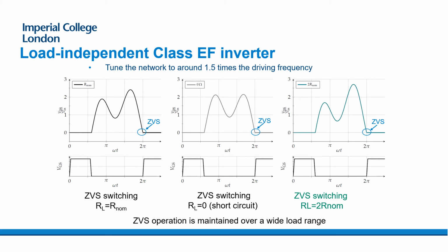on this slide, where we now have a more complex trajectory of the drain source voltage. It has additional harmonics brought about by that additional resonant network. But fundamentally, even with different values of reflected resistance here, we are maintaining zero voltage switching in all cases and consequently high efficiency. We're also, as I mentioned, maintaining a constant current in the transmit coil.